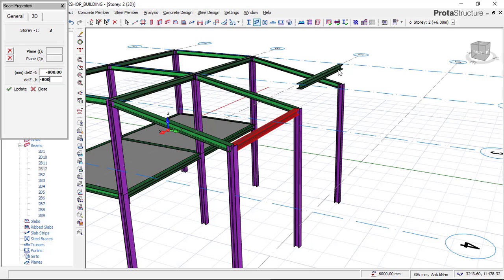Then we'll click on this place again. Don't forget, the reason why you're dropping it is to get the shape. Not that you have to drop all your beams. No, it's to get your shape from what we have right here. You can see the shape we want to achieve. So that's why we are dropping it. And that minus 800 is not a constant. It depends on the kind of model you're working on. Yours can be 1000 dropping, 500 dropping, or 750 dropping. So it depends on the plan that you have. That's what you can now work with.